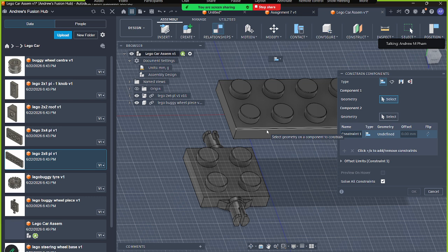That's because when you are making an assembly, sometimes your parts aren't fully fleshed out and finished, and the last thing you like to do is make it pretty and add a bunch of fillets or chamfers everywhere. When you do that, the edges you may have selected for your constraints will disappear, because you created a fillet where the edge used to be.